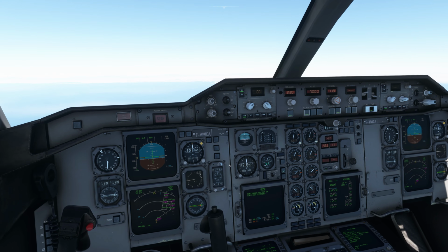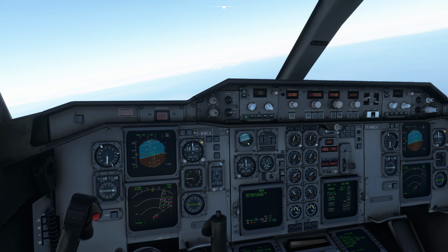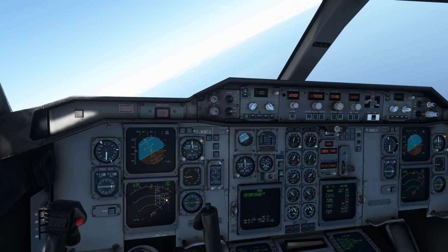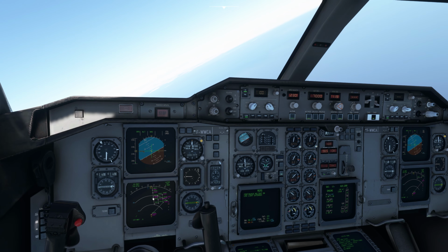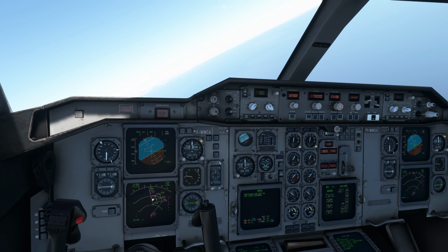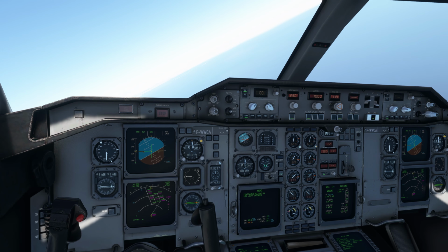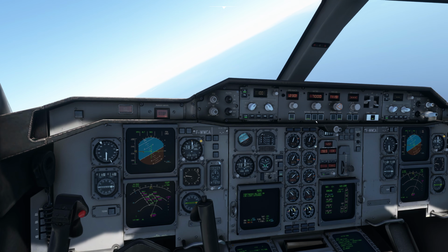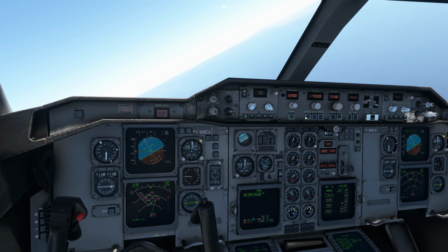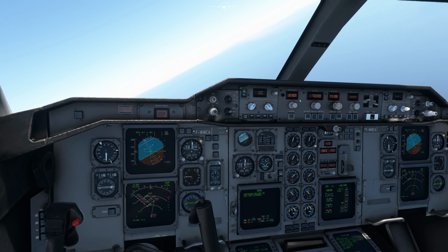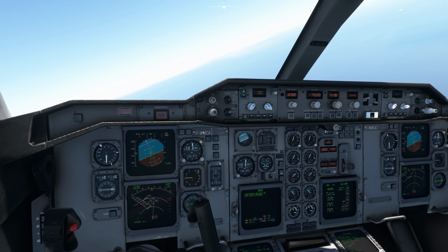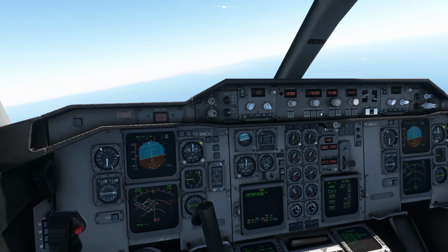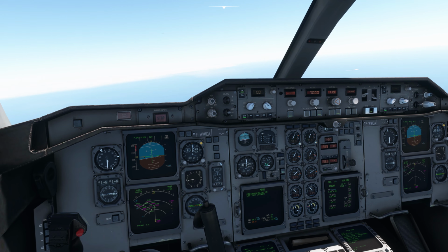If you're flying the Phoenix or the fly-by-wire, if I set it to 3,000, it will just make sure at this point it's below 7,000, and it remains at 7,000, and then 6,000. It follows all these constraints so that eventually by this point it is at 3,000 feet. But this plane doesn't follow all these. So that's why I will keep the altitude at 7,000, but I will descend in the profile mode now instead of level change or vertical speed, because then in the profile mode the speed will automatically be adjusted by the plane.